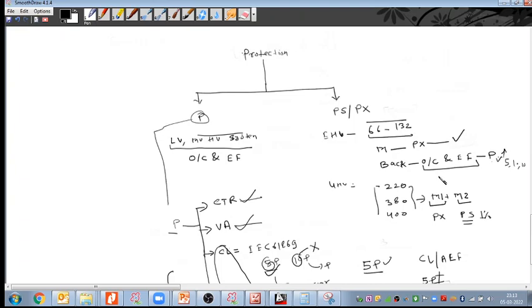Yes, Raghunath, correct. The cross section of the conductors. We can increase the cross section of the conductors in that case. Yes, Jayant. That is the one option we have, because we do not have many things in the CT. We have the conductors, the primary and secondary side.